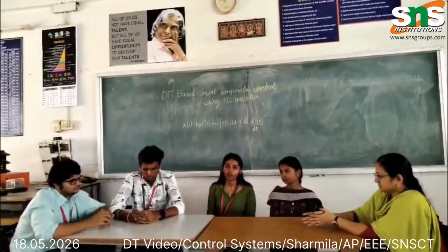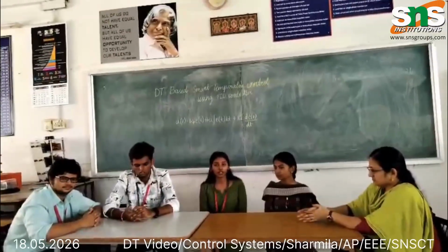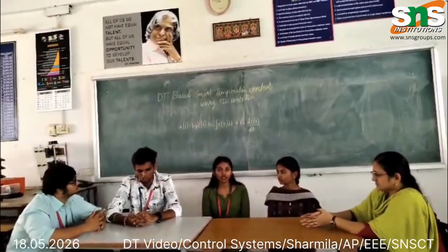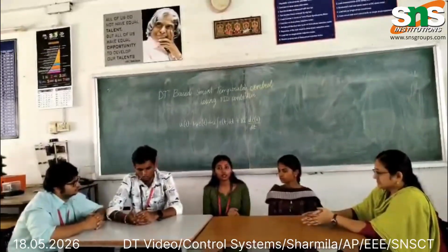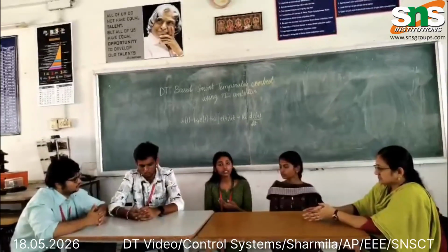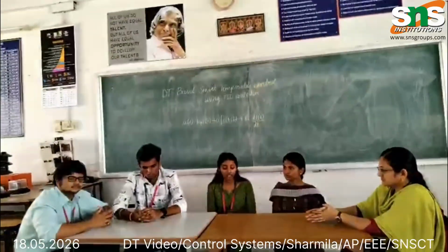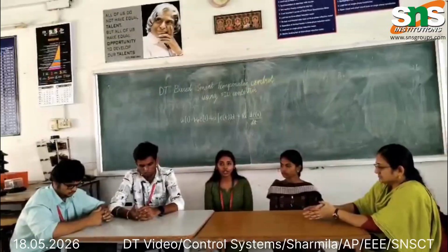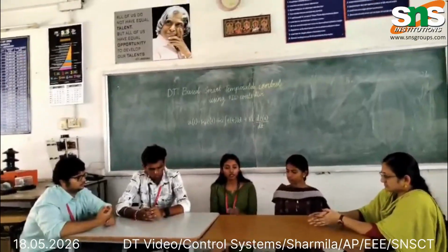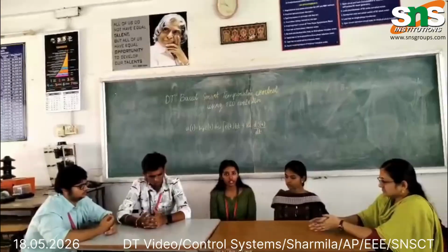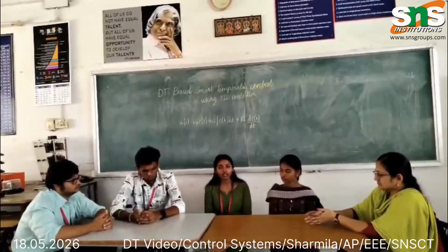After defining the problem statement, let's move to the ideate stage. In this stage, we are going to find the best possible solution to our problem statement. We have several control system methods. Our first method is the on-off controller. In this, when the temperature is too low, the heater turns completely on, whereas when the temperature is too high, the heater turns completely off. So this system is not efficient. Next, our second method is the manual control system. In this method, a person continuously needs to check the error or the temperature changes and adjust the temperature continuously. So this method is not efficient.